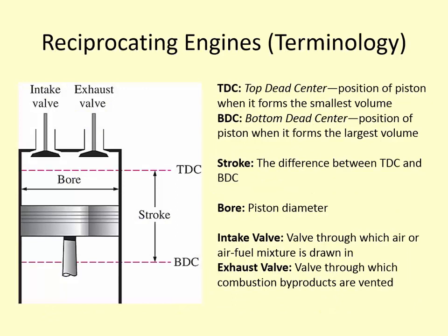Okay, so more terminology for reciprocating engines. We have top dead center, TDC, which is the position of the piston when it's at the smallest clearance volume. Okay, so top dead center is when the piston is here. Bottom dead center is when it's at its maximum volume. The stroke is this linear distance between top dead center and bottom dead center.